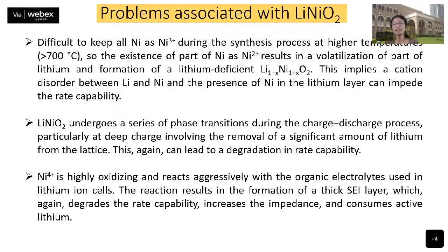And with nickel 4 plus, again, the problem is it is highly oxidizing and it reacts aggressively with the organic electrolytes. So it will lead to the formation of a very thick SEI layer, which is going to increase the electrical resistance of your battery. And if the electrical resistance is increasing a lot, then there is a problem with the rate capability as well as the capacity of your battery.